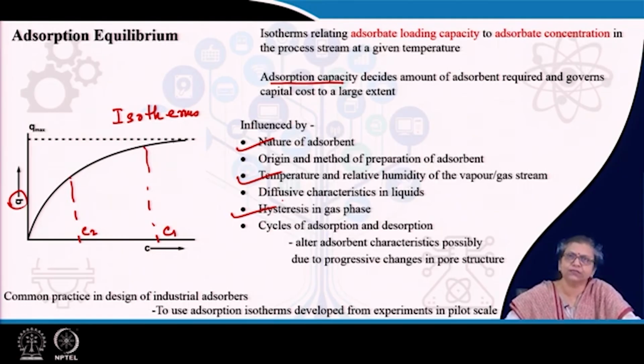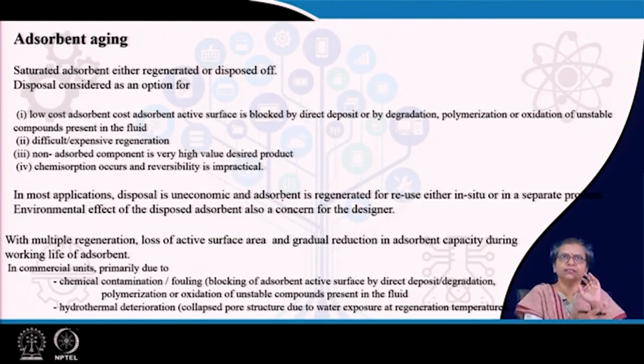Now, under that condition, what do we do? Do we just take the adsorbent and dispose of it? Yes, under certain conditions, definitely we dispose of it. Under what conditions do we perform the adsorption operation and simply dispose of it? Definitely when the adsorbent is much lower cost, under that particular condition we would do this. The other thing is when the regeneration method is much more difficult, under that condition we would go for it.